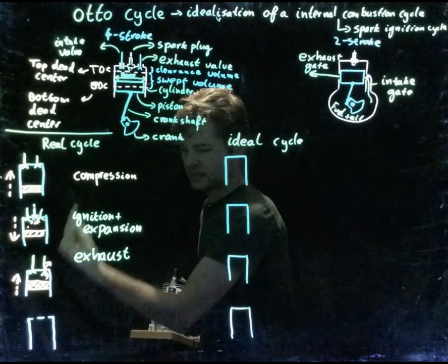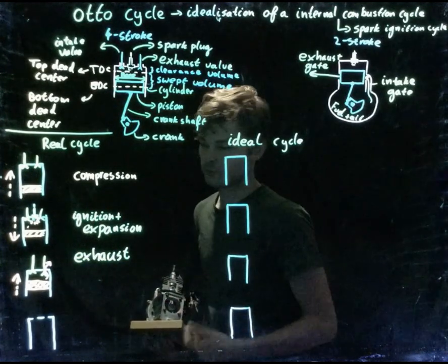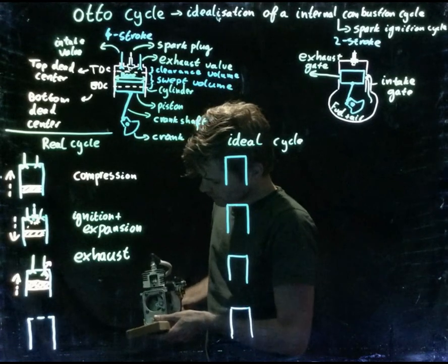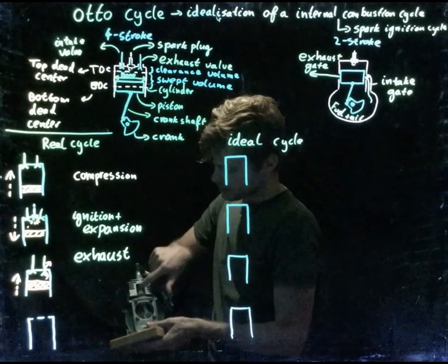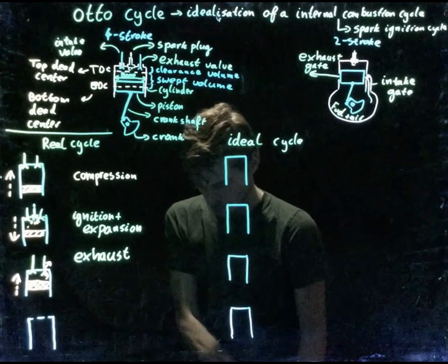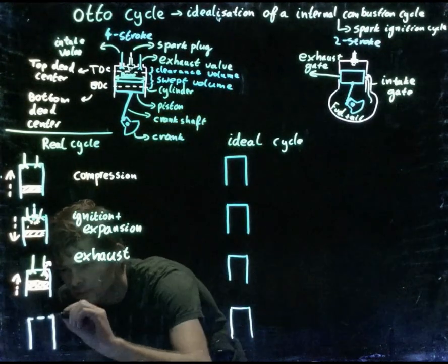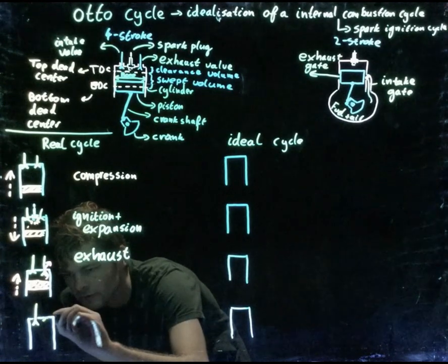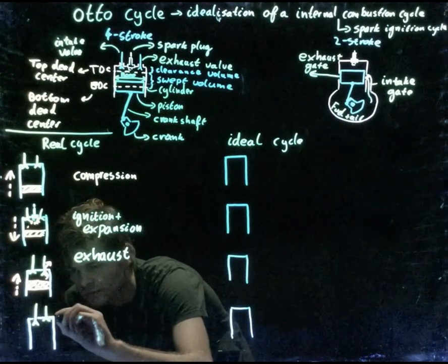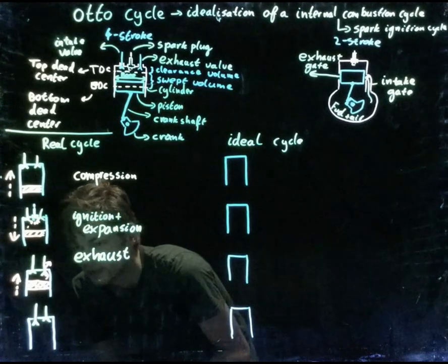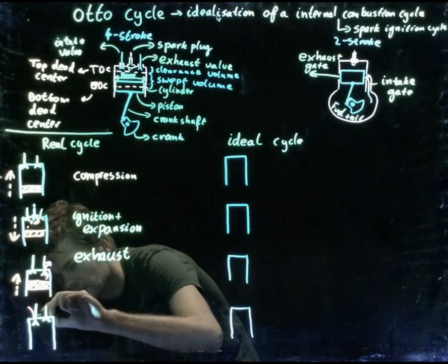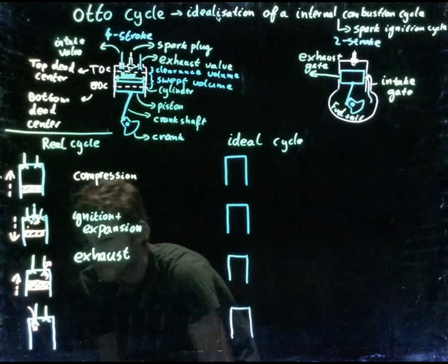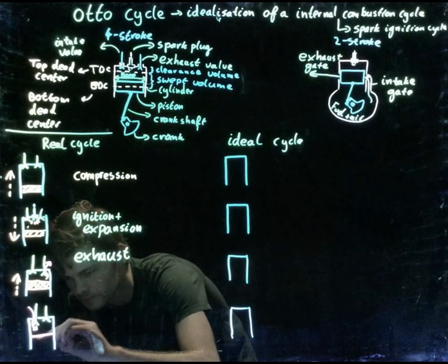So at that phase, all exhaust gases, all fumes are driven out, and when going back, slightly under pressure is created over here, and meanwhile the inlet port opens, and here the exhaust port is locked again, so no air can flow out, and that will look like this, with the piston moving down.